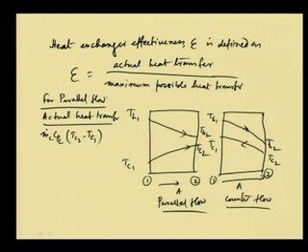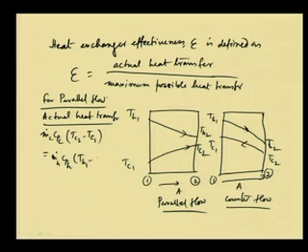So, this is the actual heat transfer, that means the heat being taken up by the cold fluid. Similarly, the same amount of heat is being lost by the hot fluid, and that will be equal to m dot h, the mass flow rate of the hot fluid, Cph, the specific heat capacity of the hot fluid, into the temperature difference TH1 minus TH2. So, this becomes the actual heat transfer in case of parallel flow.